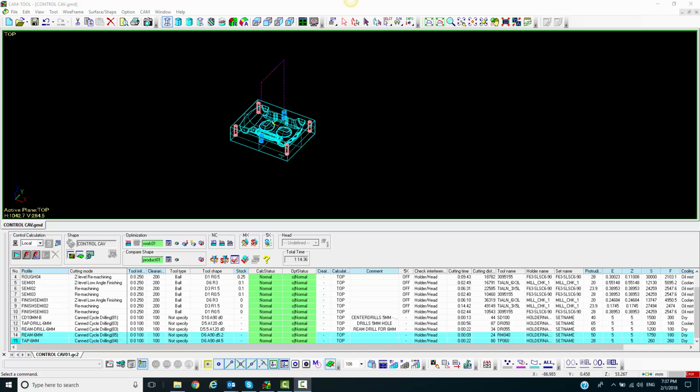One thing to be noted is that all of these drill cycles are able to be customized exactly the way you want them to run. If you're using carbide drills with faster feeds and speeds and don't want a center drill, that is entirely possible. We will get into editing the drilling template database at a later video.